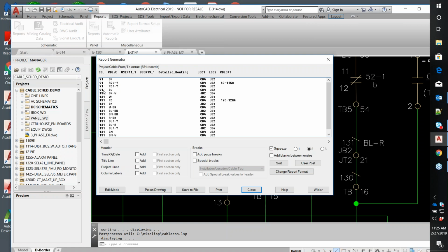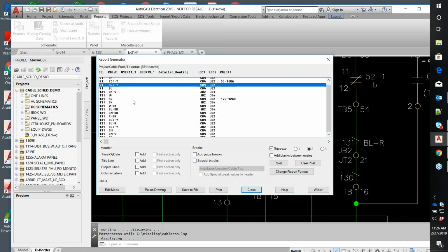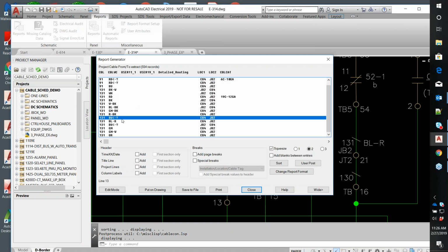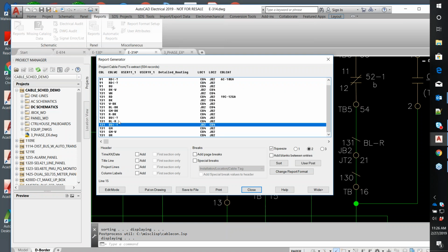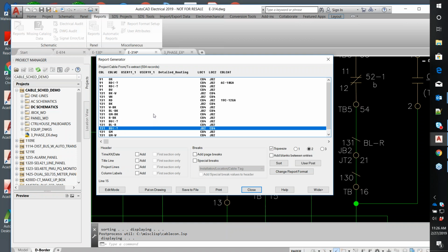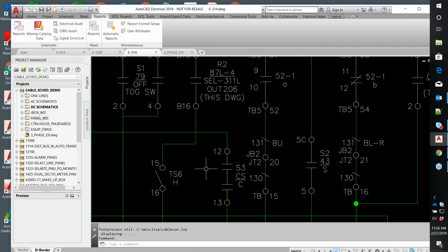So for example, it looks like it found that in cable 91, a 4-conductor cable, red is used twice. Now cable 131, the one that we were messing around with before I did the undo, it detected that yes, blue is used twice. So it shows a little arrow and a question mark pointing at it. Those 2 cables in my entire project are cables that have a color assignment that has been duplicated incorrectly. Now, what would be involved to do this by hand, just using straight AutoCAD Electrical? It would be more painful. So this report really saves some time.